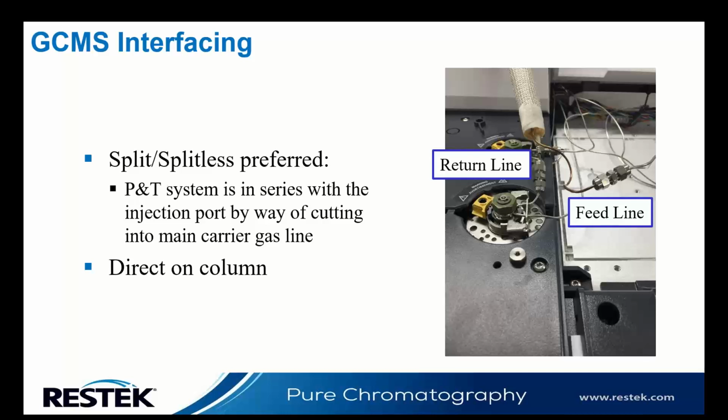And it also, you'll actually be able to see leaks from that if the EPC can't maintain pressure. So that's one other little troubleshooting thing that you'll see on a 7890. The EPCs are so sensitive that if there's a leak, it will go up and down in pressure, and you can suspect it's probably somewhere. The first place to look would be the injection port.